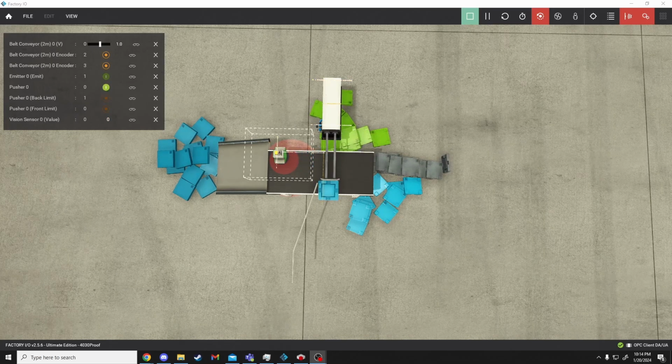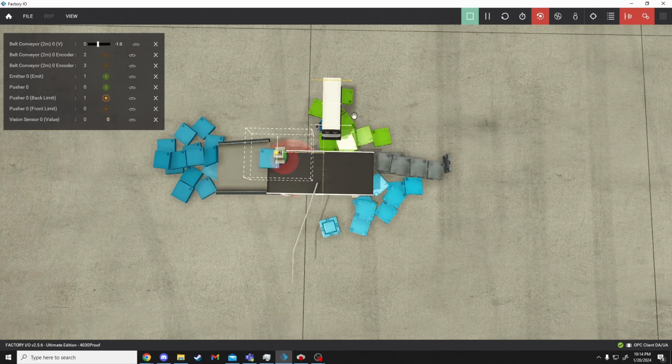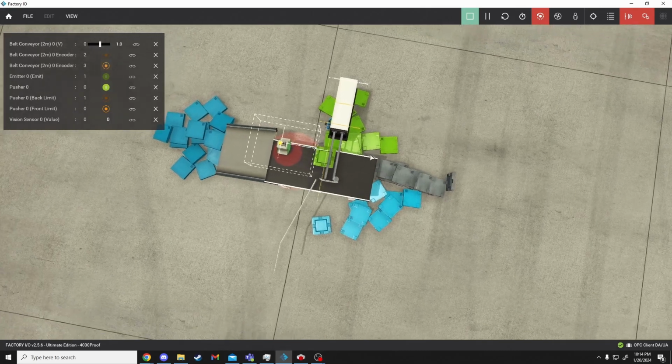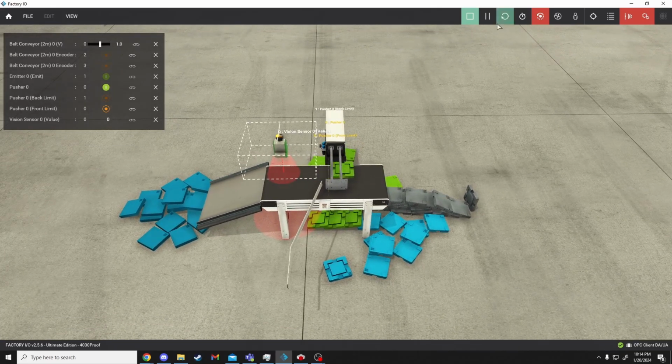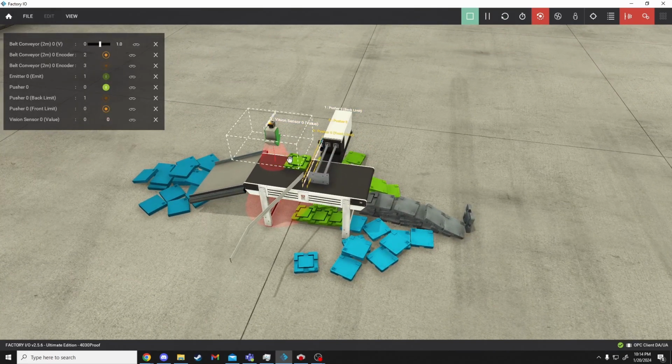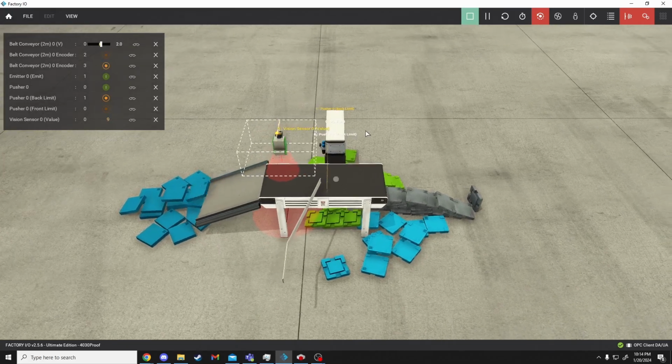What I kind of had in mind for this project was to save some costs with a system that only uses a single piston and a single solenoid valve. So basically, the goal is to reduce these pistons down as much as possible. You can see we only have one active here. Pistons and their associated control valves, the solenoid valves, are pretty expensive and would have made up the bulk of our project budget. So by getting this down to a single piston, we save a lot in the design